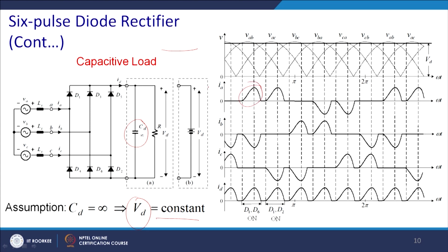So, current will flow only for this much duration, then again it will flow for AC when it goes high, similarly for BA and CA and so on. Thus you get a problem of shifted power factor or displacement power factor. So, you can see this is IA, IB, IC, and it will have a rather more nasty THD with the capacitor, and it can go as high as 70% for light load.